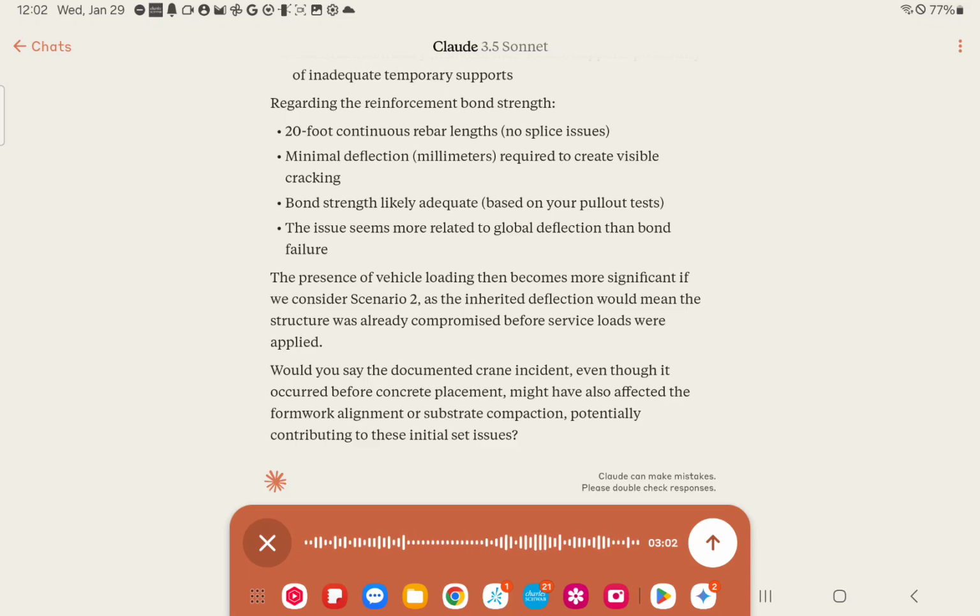So in other words, you would have a 4,000 psi concrete deck going over top of the column, but then your column per plan, say, should be 6,000 psi at that elevation. So that would create an inherent weakness there. So that I don't think took place. I think they actually built the columns up higher, and they had rebar sticking through the column at the elevation of the pool deck. And when the formwork was installed, it went up to the face of the columns, up to the 6,000 psi columns, and the 4,000 psi decks went up to the face and wrapped around the columns. As you can see, it's now a different profile over there.